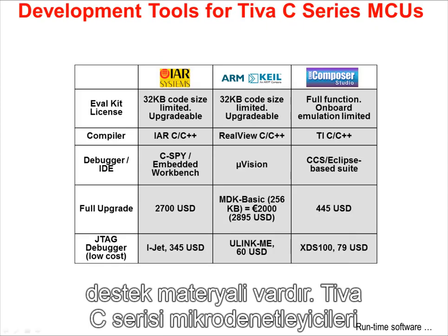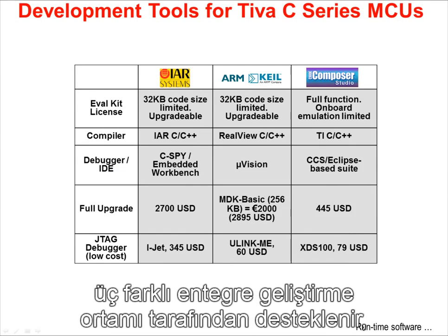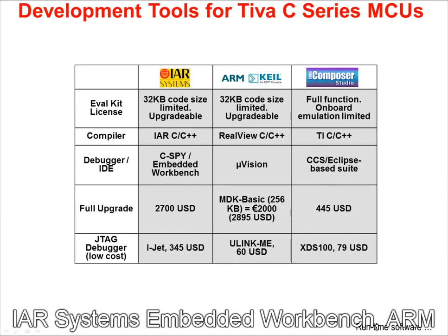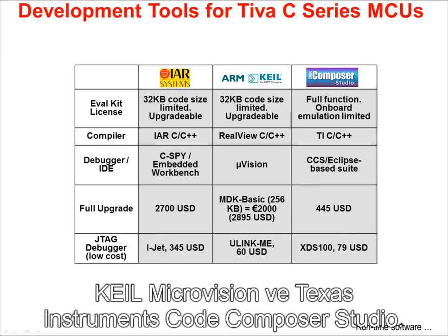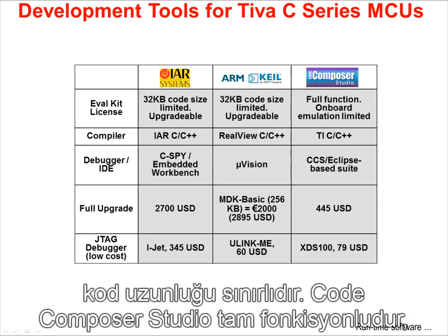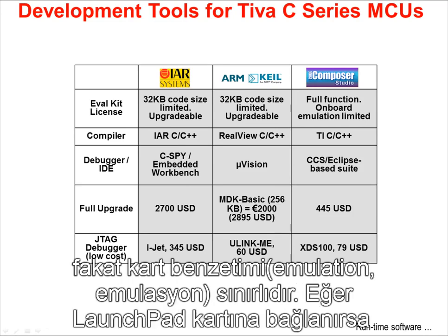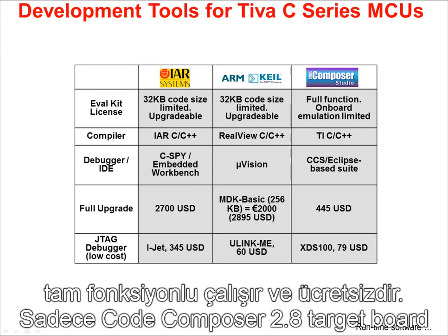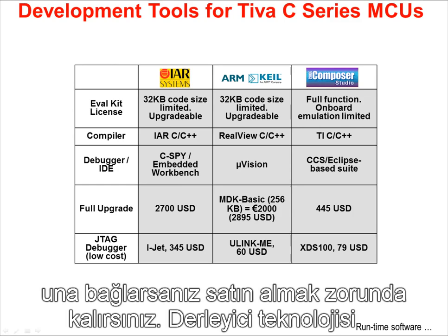Tiva C-Series microcontrollers are supported by 3 different integrated development environments: IAR Systems Embedded Workbench, ARM Keil Microvision, and Texas Instruments Code Composer Studio. IAR and Keil's evaluation licenses are code size limited. Code Composer Studio is full function, but it is on-board emulation limited. When connected to the LaunchPad board, it is fully functional and free. Only if you connect Code Composer to a target board will you need to buy it.